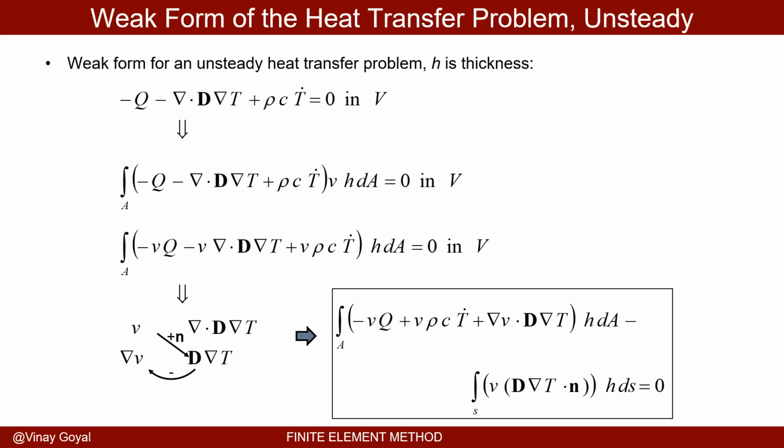So what is the first step? This is the differential equation. It's actually a partial differential equation, which now depends on X and Y, but also depends on time. So how do I tackle that? I multiply this equation by the residual and by a weight function. The one thing I want to remind everybody is, what is the unknown here?